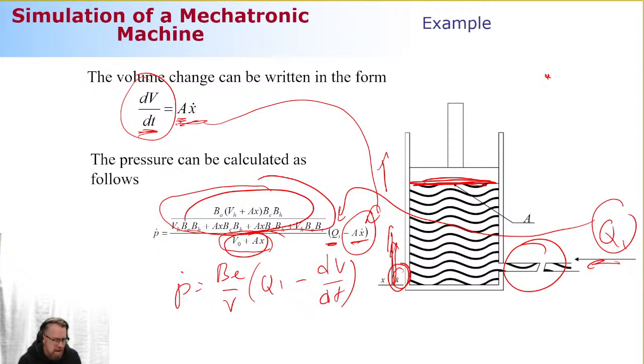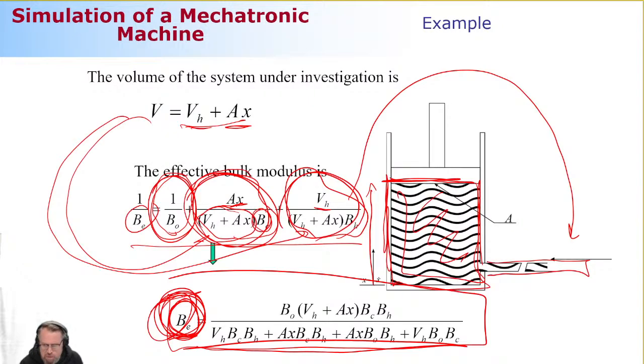Makes sense? Okay. Again, maybe I did not mention this clearly earlier, but it's very important to be consistent. I have seen people lose their mental health because they don't make this drawing. They simply assume that they will remember which is the positive direction all the time. They remember for 2 minutes and then it's gone from their head. Then they create the needed differential equations and make an awful lot of mistakes with pluses and minuses. If you think that the flow rate is leaving, but it's actually coming into your volume, you can understand the consequences. The pressure is behaving completely incorrectly. You can get pressure values that make absolutely no sense. So lesson learned: make a drawing, be consistent. Okay? Makes sense.